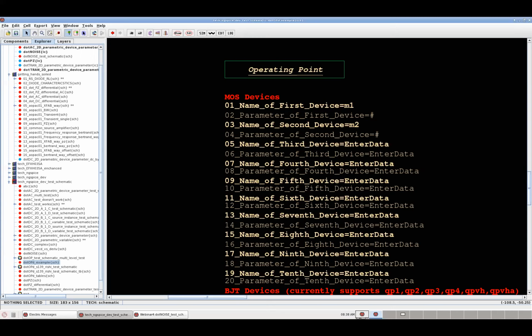Okay, in the AC analysis, I don't know what kind of operating point the AC is being solved around. If my circuit is taking time to settle or reach a stable operating point, and I want to do an AC analysis around this point, it has to wait until it gets the solution at that time, then it uses the operating point at that time in the AC solution. Can we do something like that in here?